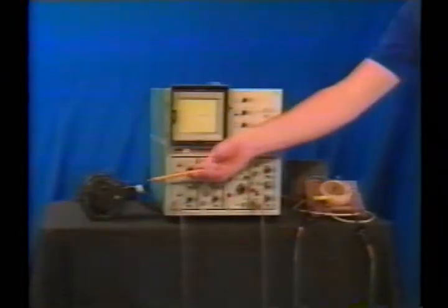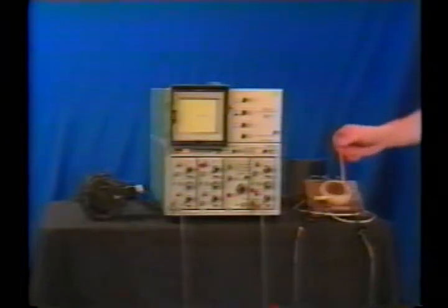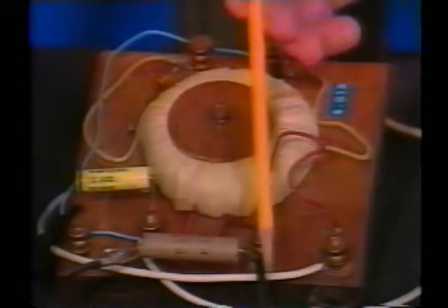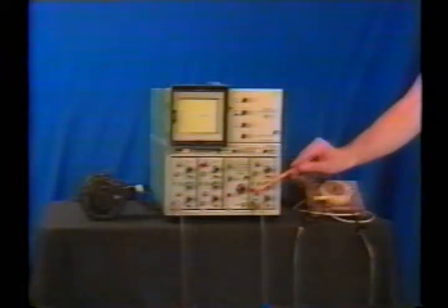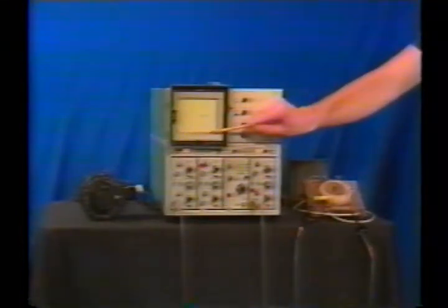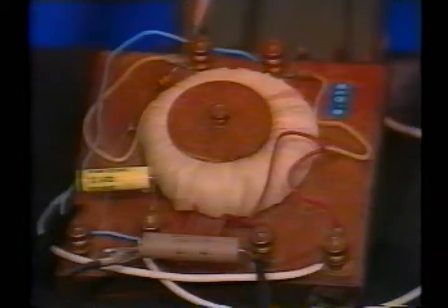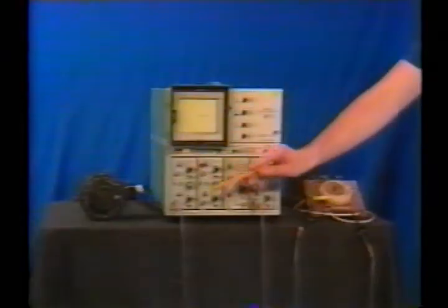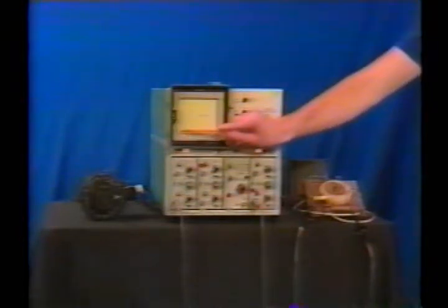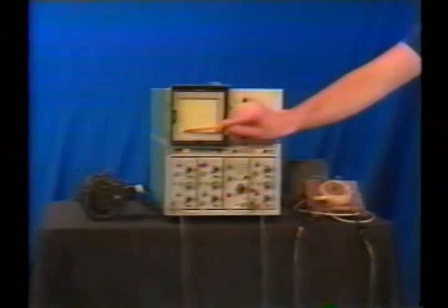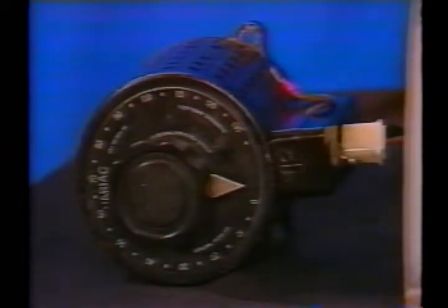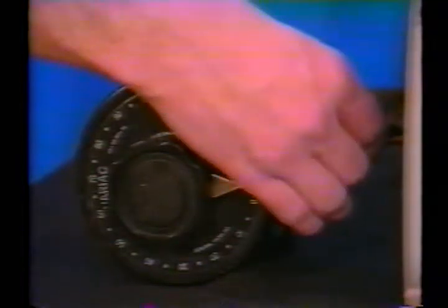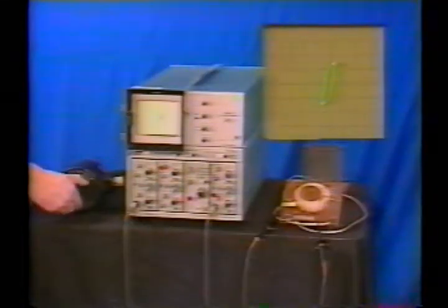We turn up the variac current. The scope shows the BH hysteresis loop typical of a magnetically soft material. For our primary coil of 83 turns, the major radius is about 3.2 centimeters. The current viewing resistor on the primary coil is 1 ohm. Thus, the scope scaling factor relating H to V1 equal IR1 is 413. With a horizontal scope scale of 0.5 volt per centimeter, each scope horizontal deflection of 1 centimeter is about 210 amps per meter.